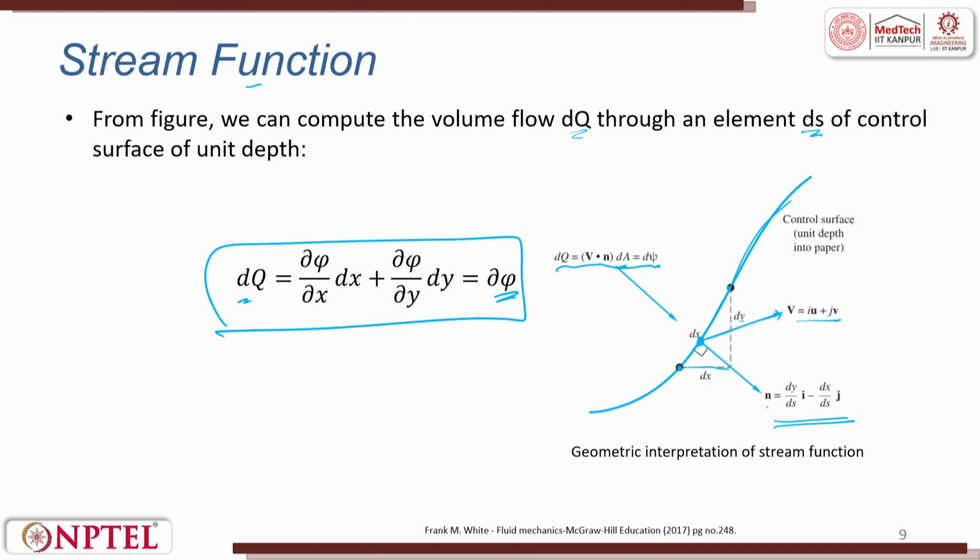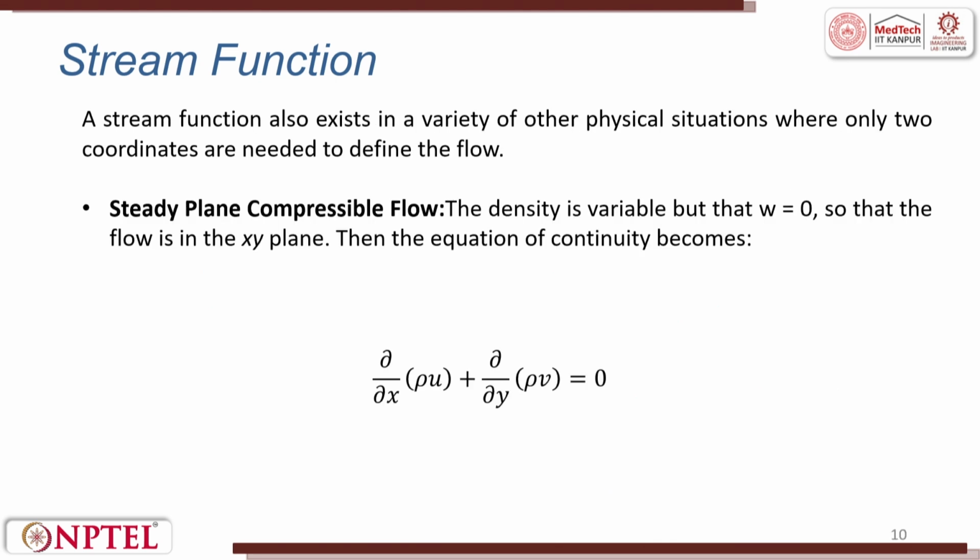So, it is into the paper. So, this is the geometric interpretation of the stream function. So, we can compute the volume flow dq from stream functions. A stream function also exists in a variety of other physical situations when only two coordinates are needed to define the flow. We use the stream function.